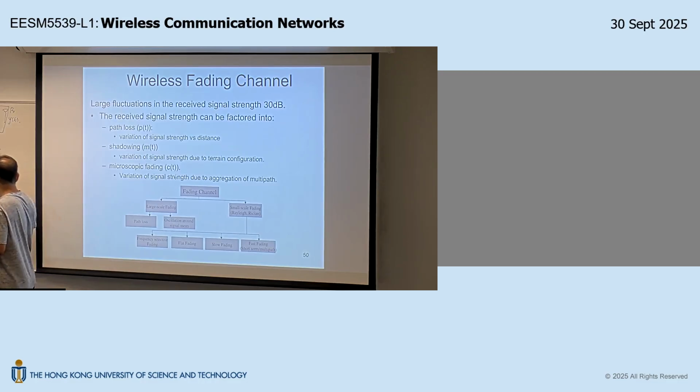So if you want to fully characterize this LTV system, you need to construct or you need to know this two-dimensional impulse response. Okay. Now, of course, knowing the two-dimensional impulse response would be more tedious compared to the case where the impulse response is just a one-dimensional function. So you need to capture the time variation component as well. Is that okay? But conceptually, it's the same.